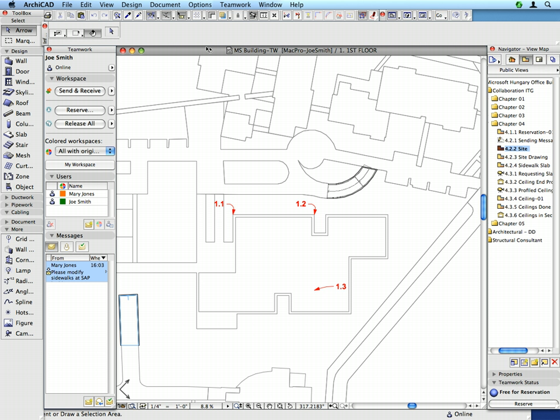The X and Y coordinate, radius and angle values are always relative to the horizontal and vertical directions of your screen, and they do not rotate along with the rotation of the floor plan. This is also true for the values displayed in the Tracker palette.